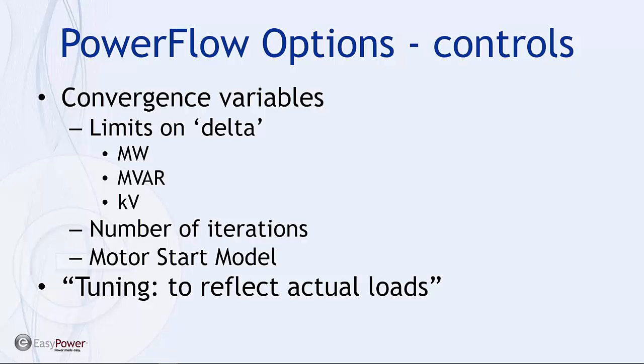And then in addition, we're going to talk about tuning, because that's probably first and foremost the best way to modify the model that we use for arc flash analysis or short circuit analysis, because it's more ideal and based upon nameplate data, whereas the PowerFlow will be based upon how the system's actually operating, which may be far different from the total design limits of the equipment involved.